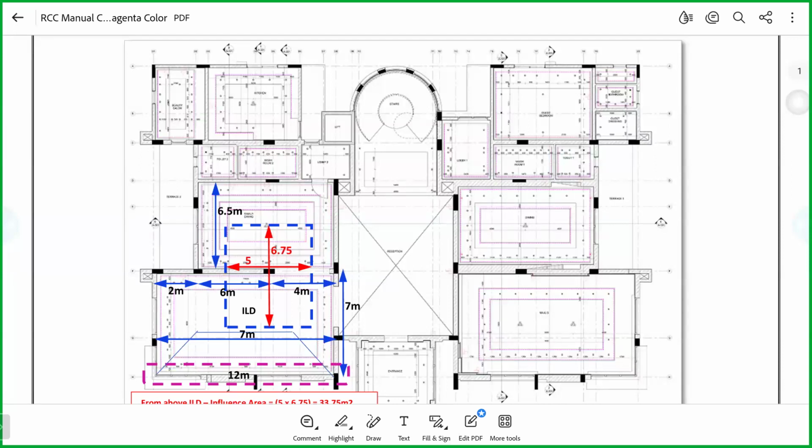Okay, we can look at the bigger span here. This span is actually 6.5 meters, and this one is actually 6.24. The reason it has been given a separate dimension is that we have multiple columns here. So we wanted to show you directly how to calculate the beam as well as the column and foundation. In general, the load is transferred typically from slab to beam, beam to column, then column to foundation. Is that clear? This is the loading part.